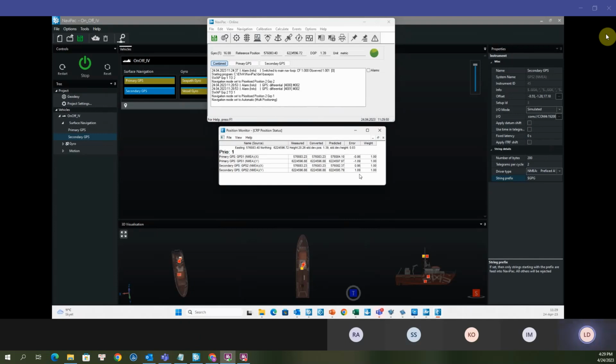But try to imagine a situation where we know that the primary is an RTK solution, for instance, and the secondary is some sort of code differential solution. And that means that the primary is perhaps 5 times better than the secondary. That could be 5 centimeters horizontally against 25 centimeters horizontally, 1 times sigma. How can we use that information?